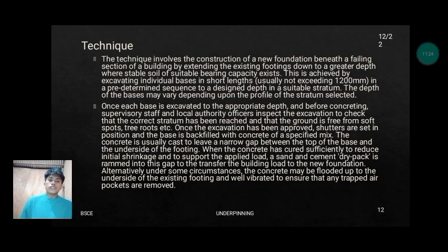The technique involves the construction of a new foundation beneath a failing section of a building by extending the existing footing down to a greater depth where stable soil or suitable bearing capacity exists. This is achieved by excavating individual bases in short lengths, usually not exceeding 1,200 mm, in a predetermined sequence to a design depth and a suitable stratum. The depth of the bases may vary depending upon the profile of the stratum selected.